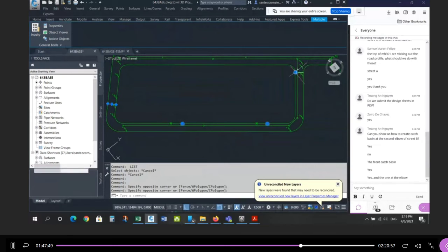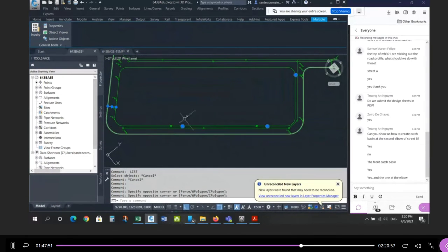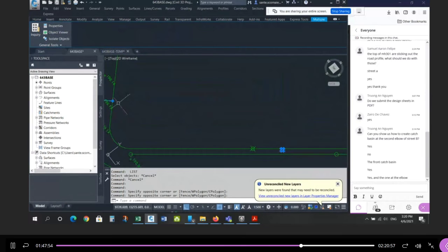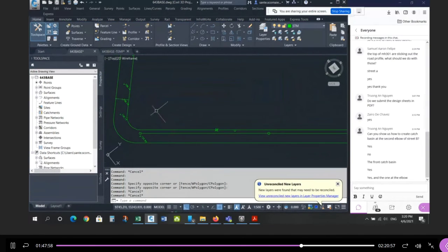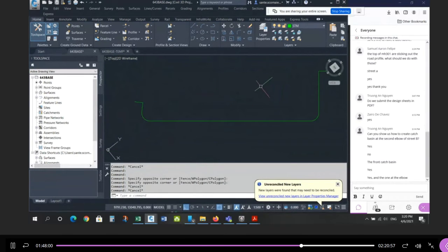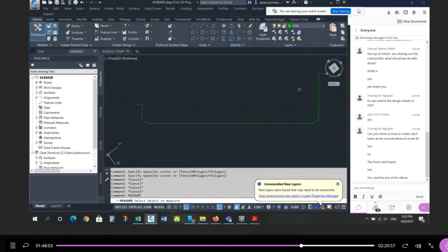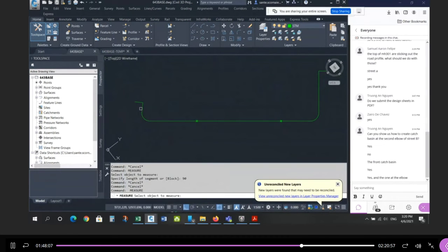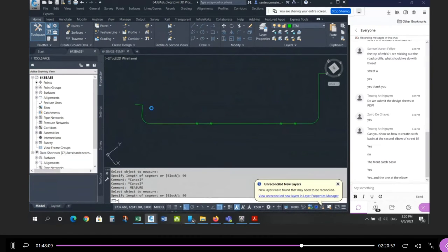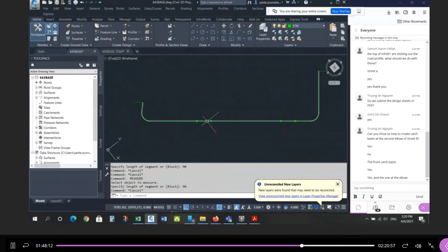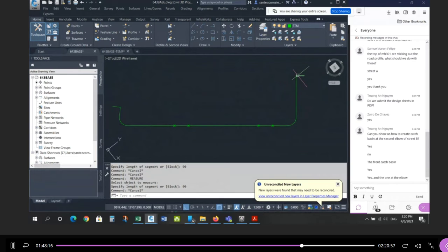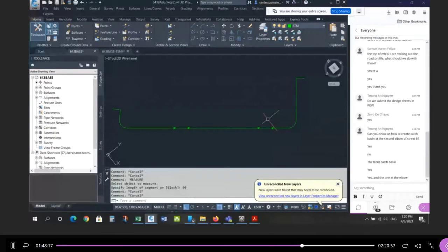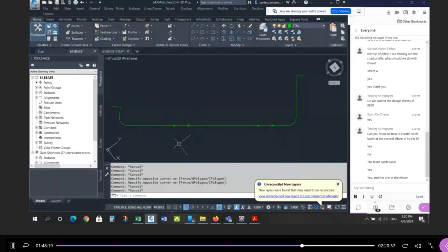As long as the distance between the catch basins is 90 meters or less. And you can treat the high point as if it's a catch basin, right? 90 meters from here. I could do the measure command from either end, right? I could start here and go uphill 90 meters, or I could start here and go down 90 meters. Right, so now from here, this is 90 meters. From here to here is 90 meters. And now from here all the way to here is less than 90. So the catch basins are going to be somewhere between these 2 points and these 2 points, approximately.